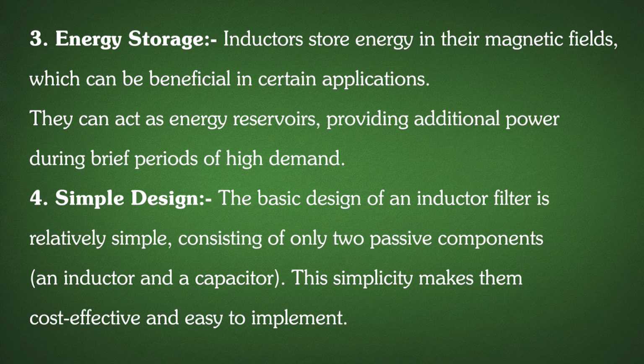Next advantage is the energy storage. The inductors store energy in their magnetic fields, which can be beneficial in certain applications. They can act as energy reservoirs, providing additional power during brief periods of high demand. Next advantage is its simple design. The basic design of an inductor filter is relatively simple, consisting of only passive elements like inductor. This simplicity makes them cost effective and easy to implement.